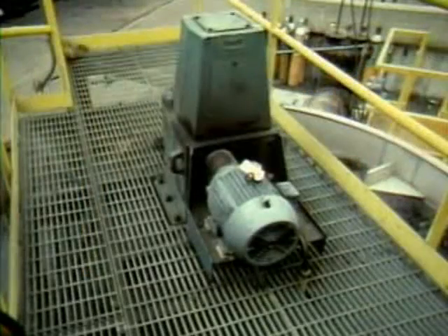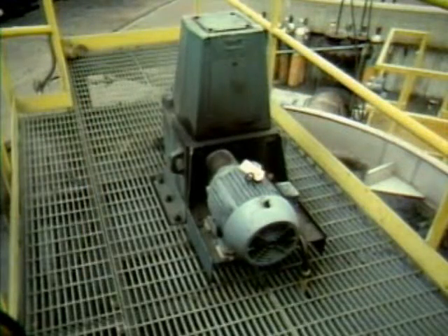Twisting stress is predominant in rotating machinery, like the shaft assemblies in motors and pumps. If the twisting stress is greater than the design limits of the shaft assembly, the equipment could be damaged. The weight of a girder applies shearing stress on the bolts. If the stress is great enough, the bolts can be literally sheared in 2. All plant equipment is designed to operate under some stress, but it has to be operated within its design stress limits. If it's not, it's subject to damage.